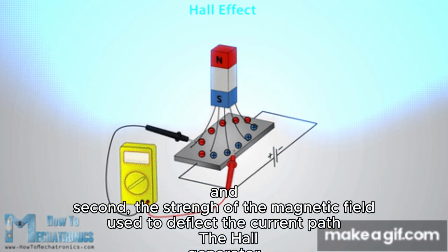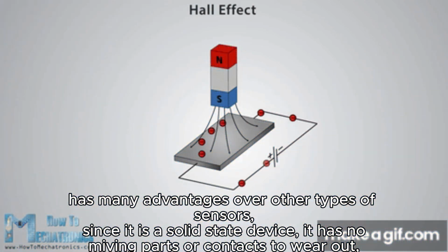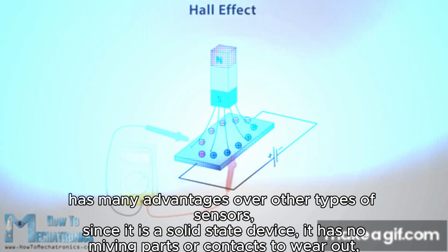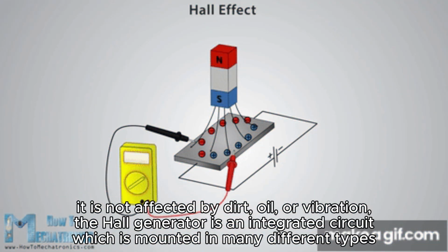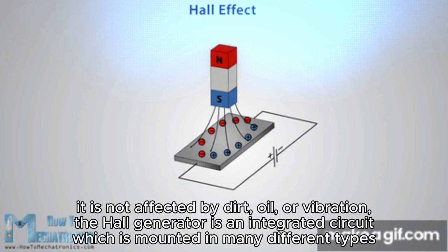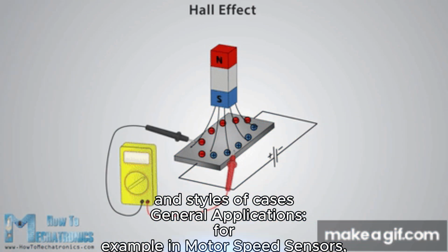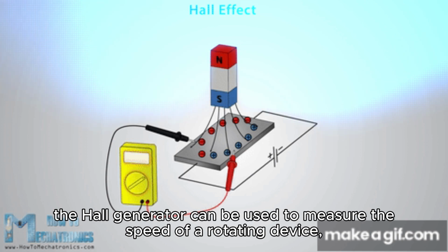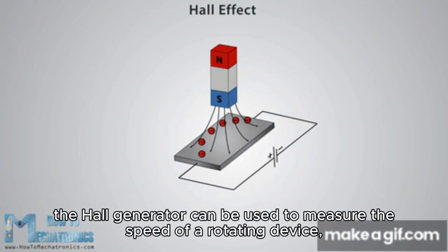The Hall generator has many advantages over other types of sensors. Since it is a solid-state device, it has no moving parts or contacts to wear out. It is not affected by dirt, oil, or vibration. The Hall generator is an integrated circuit which is mounted in many different types and styles of cases. General applications, for example, are motor speed sensors. The Hall generator can be used to measure the speed of a rotating device.